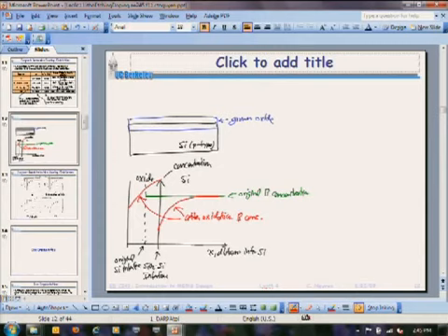And so that's what that homework problem is trying to get you to figure out. If I had phosphorus and boron initially, but boron dominated, then I grew an oxide, what do I have at the surface? Is it still boron dominated, or did phosphorus come up and become the dominant dopant there? And if it did, then maybe I have a diode now at the surface instead of a conductive layer. So it's a very practical problem to understand.